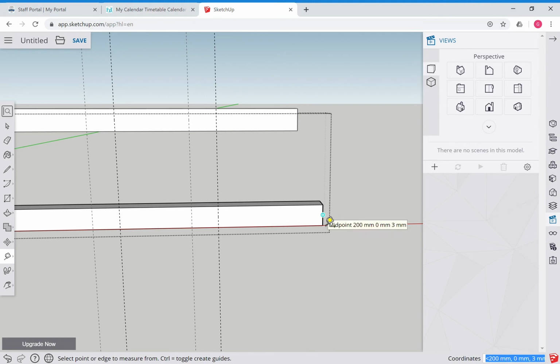Over here I'm going to go 20. So the first thing I do is find the blue, click once and then drag it, and then go 25. Enter, and it goes to 25. So that's how you do that. So you can mark out lines using the tape measure tool, and that's a useful tool to have too.